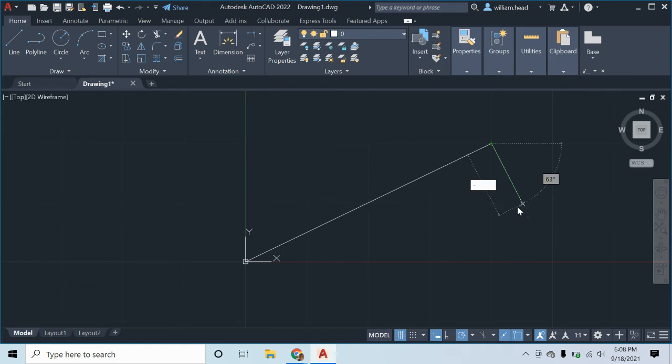So it looks like it's going to be -1. And then comma 0. No. My apologies, it is 0, because the first number is the x direction. So if I want to go straight down to here, I don't want to go left or right. So I type in 0, comma, and then -1. There we go.